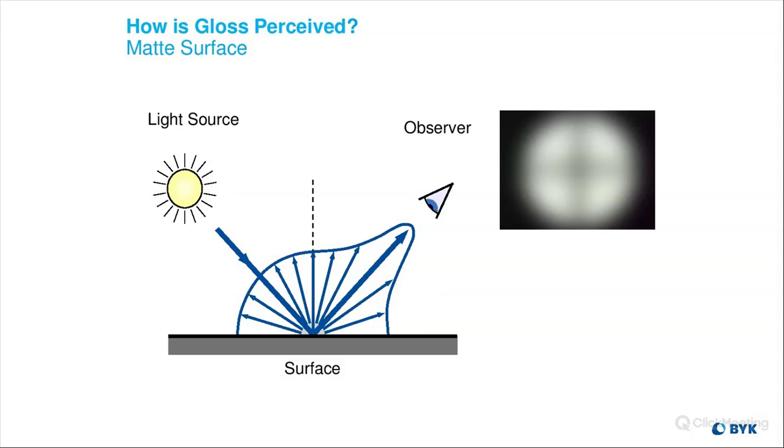Next question here. My company produces packaging film, often for the food industry. We typically measure gloss on transparent film that's 3 mil thick or less. Do you have recommendations or best practices? Again, kind of back to what you said, if you're measuring anything that's transparent, you're going to need some sort of background behind it in order to be able to measure that gloss. Without it, the light is going through the transparent material. You're still going to get a value, but it's going to be a skewed value versus applying a correct background.